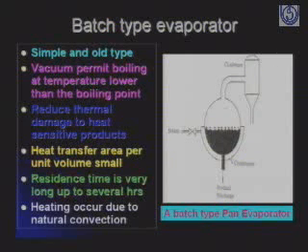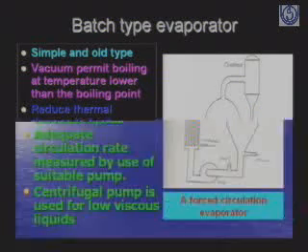So the heating here occurs due to natural convection. Why? Because this is a liquid, and steam is passed to the liquid, so that it starts to concentrate by boiling. Then vapor is produced, the vapor goes upward, and from there it can go outside, and the product after concentration settles on the lower side. You can see in the figure where the product is received.